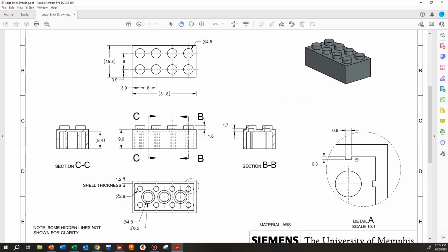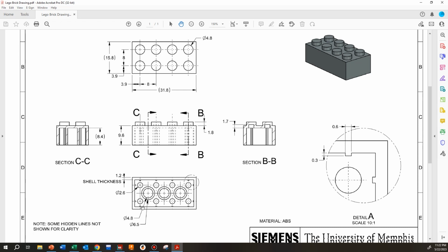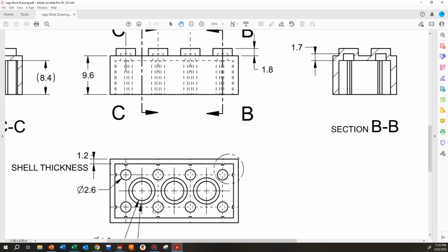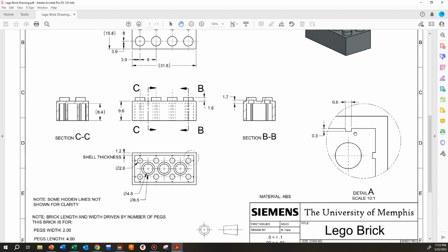Next, we've got these rectangle sticky outy bits that we have on the side. We have them all the way around the brick. We're going to do something similar, but then we're going to add to it. So we have the bits dimensioned on this side at a 0.6 millimeter and a 0.3. We know that it lines up with the emboss.